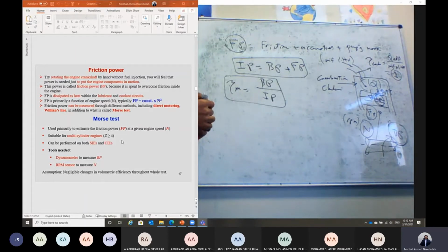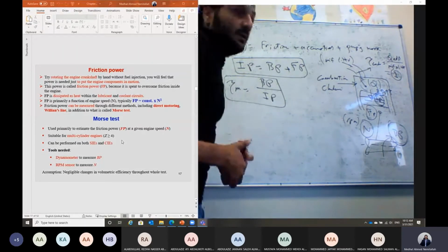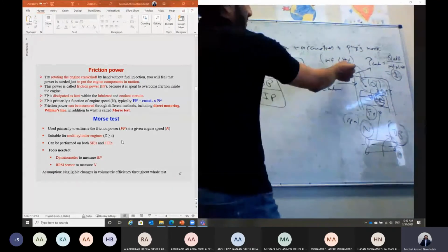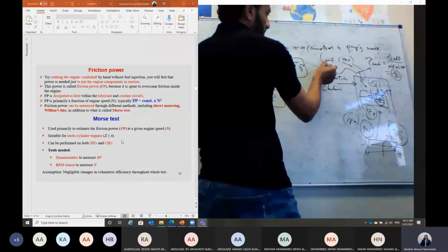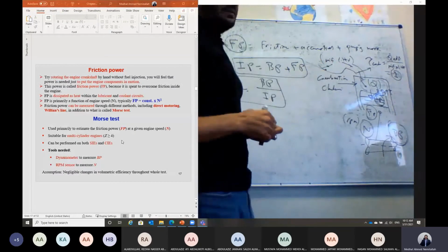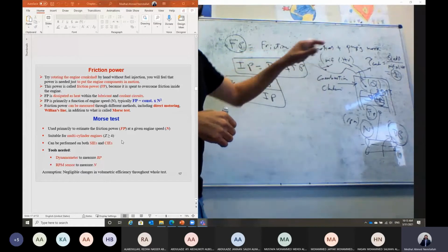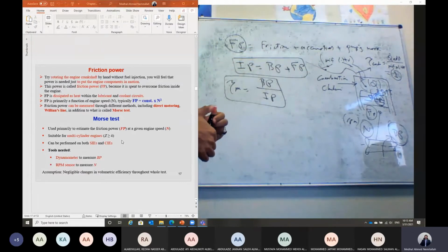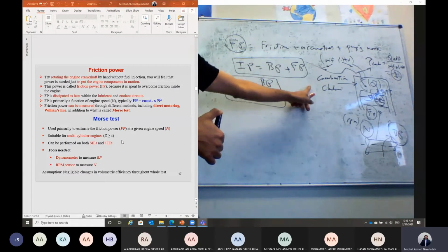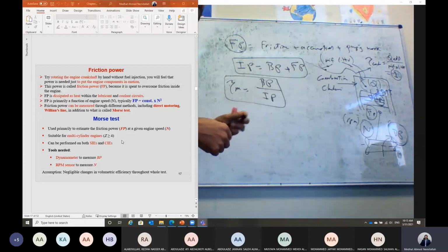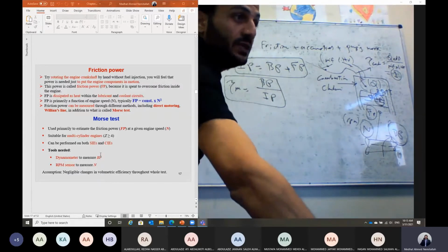power. This brake power, Shabab, at part load, the throttle valve here will be just through the intake manifold here. The throttle valve actually will be just opening a small opening in this case. So the pressure will be reduced, and the mass flow rate of air to the engine will be reduced, and accordingly the mass flow rate of fuel will be reduced, and the power of the engine will be reduced. That means at part load condition, and we have said this last time, the mechanical efficiency of the engine will be reduced.